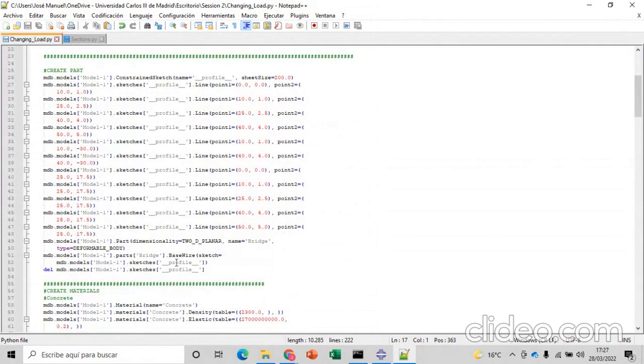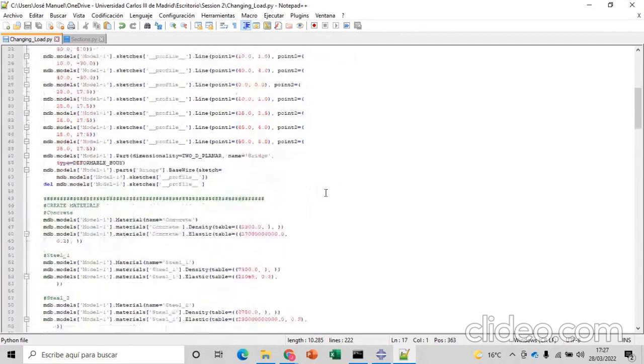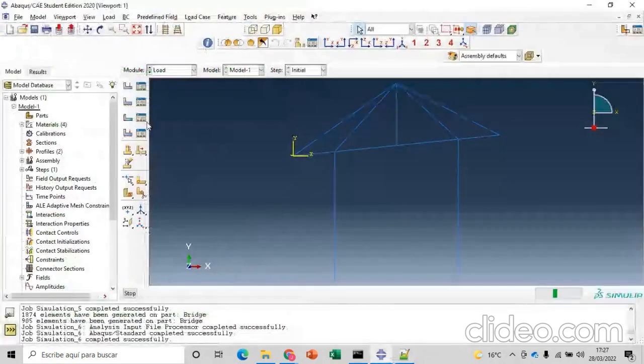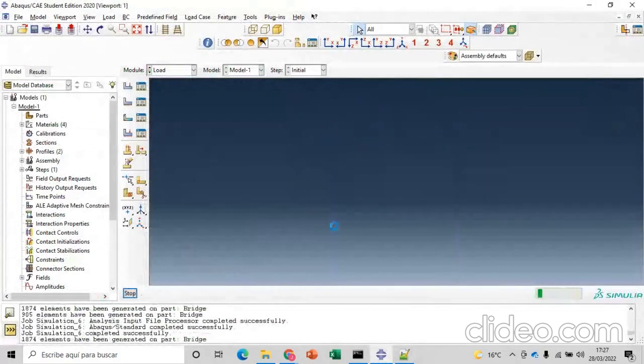And if, for example, in your simulation this bar does not reach the limit or even is supporting too much stress, you can create 10 different values for this section in order to find the best one to optimize the weight of your bridge instead of creating manually each section.